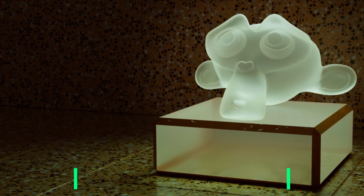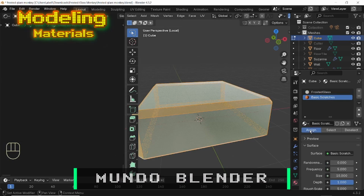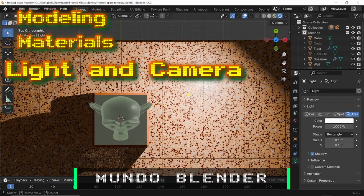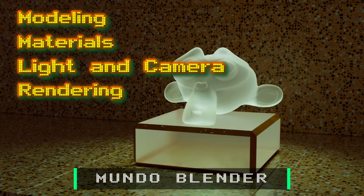In this Blender tutorial, we'll create the scene from scratch. We'll be modeling the wall and the floor, assigning materials to all objects, positioning the lights and the camera in the scene, and finally rendering the scene with the Cycles engine.